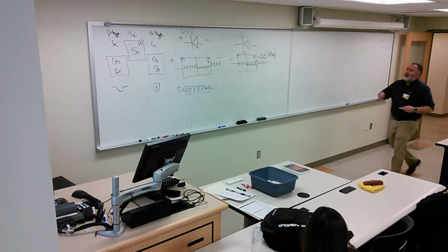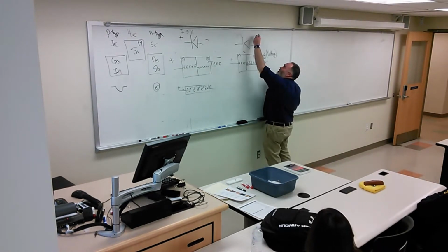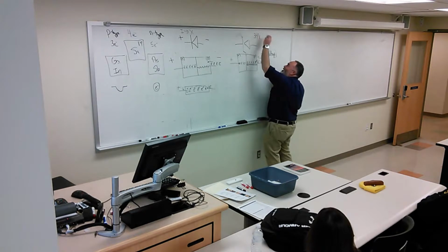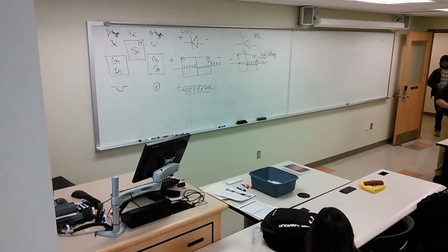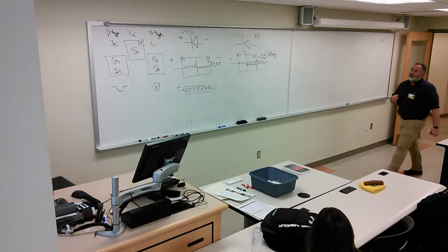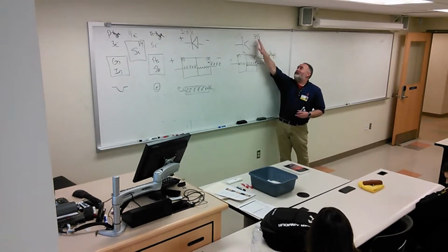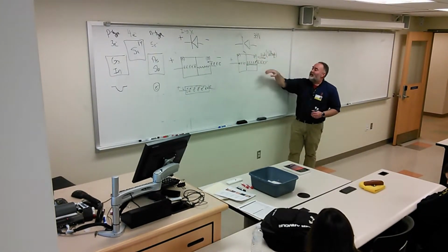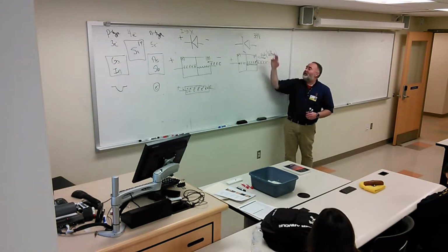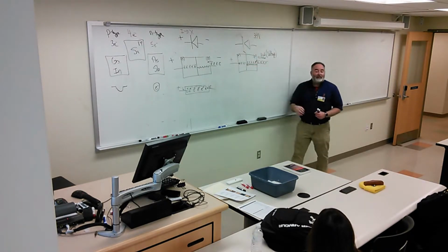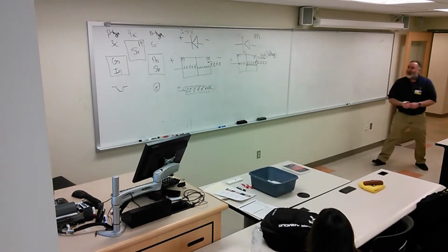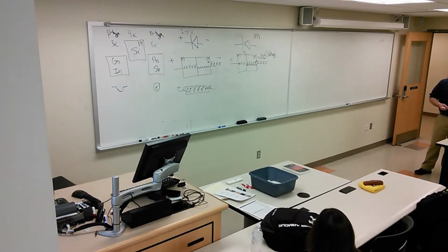Yeah, another analogy. The Zener diode that we used inside the lab last week was a 3.9 volt Zener diode. The reason why we call it a 3.9 volt Zener diode is because you need to push on it with at least 3.9 volts before current will flow. If you don't push on it with at least 3.9 volts, and that's the number they give it, it's not cut and dry. But as you start pushing with voltage, these electrons start to fill up these empty spaces, and then once they fill it up completely, then things flow. Okay? That's our Zener diode with our N and P semiconductor.